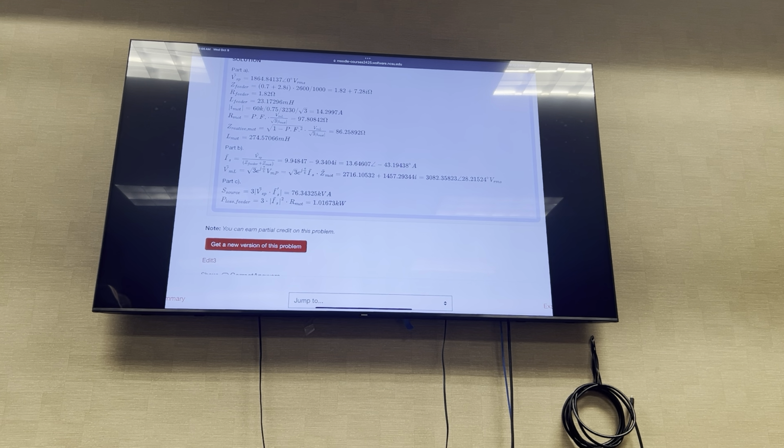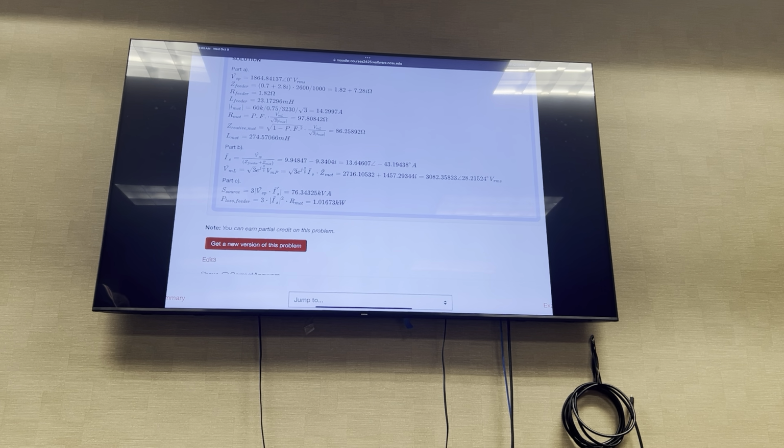They should be off by a root of 3, absolutely. It's a delta connected generator. They're nowhere near off by root 3. One uses the rated voltage and the other uses the source phase voltage. Okay. So I showed it, I don't know why, it's just what the calculation is. They're way off to be a calculation error, and they're too close to be a square root of 3.